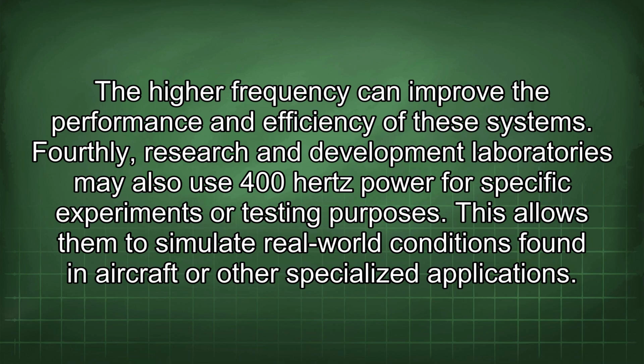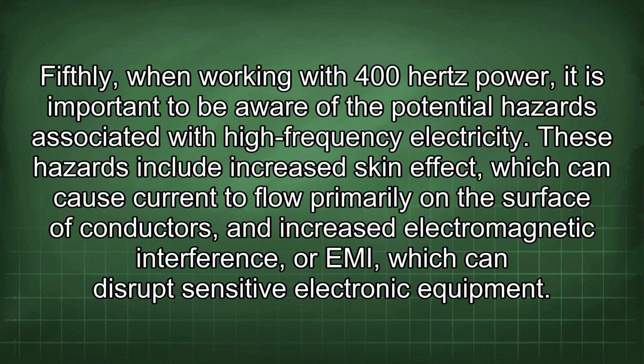This allows them to simulate real-world conditions found in aircraft or other specialized applications. Fifthly, when working with 400 Hz power, it is important to be aware of the potential hazards associated with high-frequency electricity. These hazards include increased skin effect, which can cause current to flow primarily on the surface of conductors, and increased electromagnetic interference, or EMI, which can disrupt sensitive electronic equipment.